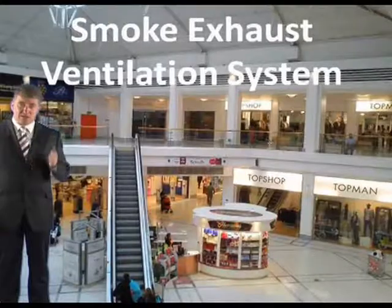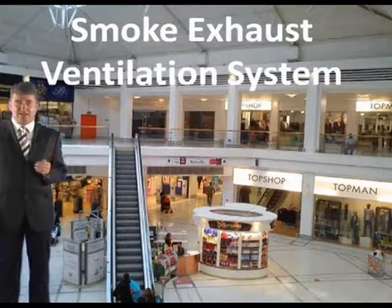Now, sometimes in atriums it's possible to use the buoyancy of the smoke gases themselves to create this required depressurisation effect, but this is rarely the case. Very rarely they use this. Generally, you have to create these pressure differentials with fans, extraction fans, for example. And finally, we have smoke exhaust ventilation systems.